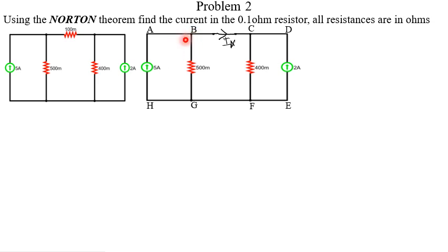There will also be a split here, so current will also leave here. So the 5 amp, to get the current flowing here, this one is also entering. KCL says sum of currents entering is equal to sum of currents leaving. So here, since we know the current is 5 amps, it becomes 5 minus IN, because those entering is to get the current leaving here. Those entering is equal to those leaving. And the total current that was coming is 5. So doing our mathematics, that is what we get.